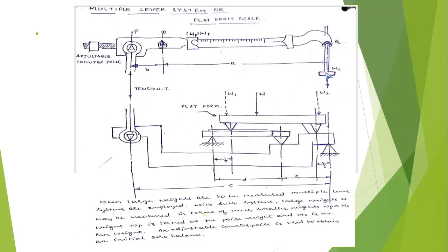For that reason, you place 20 into 1, 10 into 2 dead weights on the hook provided here, and there will be a counterpoise that can be moved in the forward direction. Place the counterpoise exactly at 6 kgs here. All of you observe here. There will be a sharp edge that you can move and place on the 6th graduation. So here it is 20 into 1, 10 into 2, 40.